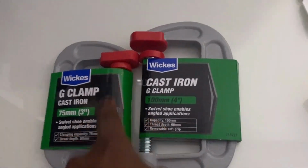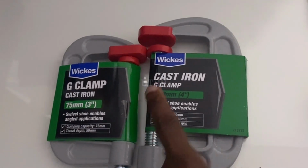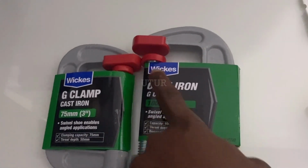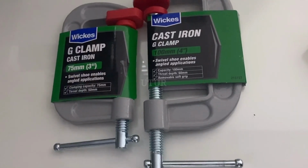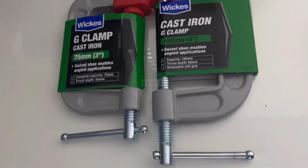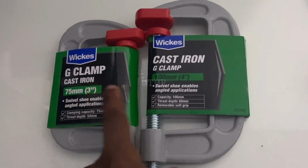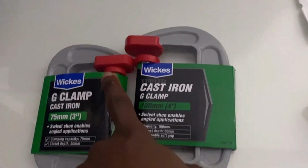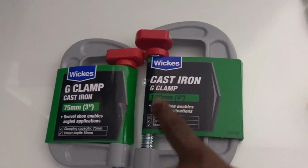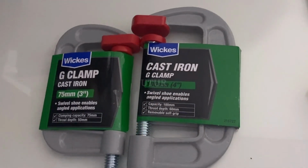So here we've got 2 G clamps. One's got a capacity of 75 mil and the other has got a capacity of 100 mil, which is the thickness that it can clamp. The 75 mil G clamp has got a throat depth of 50 mil, and the 100 mil G clamp has got a throat depth of 60 mil, which is how far the hardwood plywood board can go in. To ensure that there isn't play when we're stripping the hardwood plywood, we will be using two clamps to secure it and prevent movement.